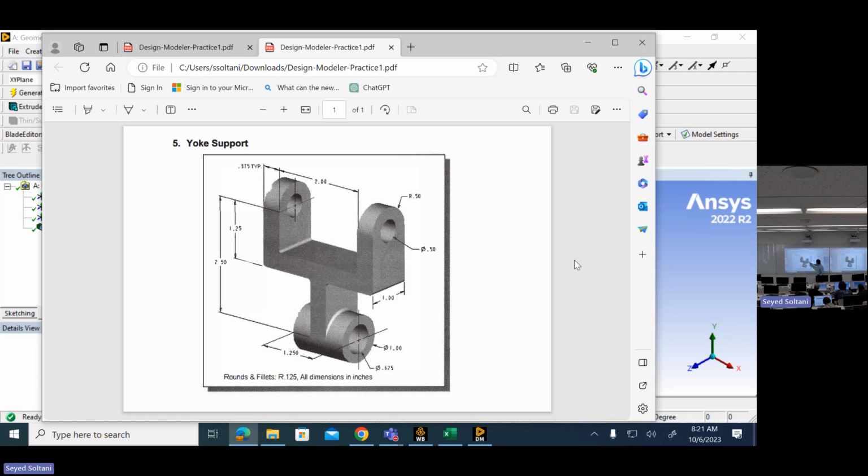All right, so in order to build this, I create one rectangle with these dimensions, 1 by 1.25 from here to here, and then I'm going to add the circles, this one and this one. The radius of this larger one is 0.5, which is going to give us obviously the diameter of 1 with the tangential at this point with the rectangle. And then there's going to be this circle. I'm going to trim out the extra edges, and then I'm going to extrude it by this much.